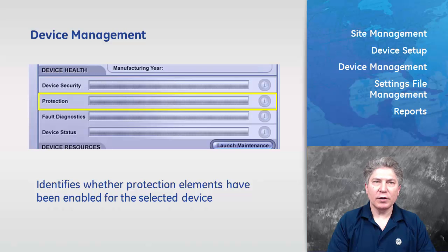If it's yellow, then the CT primary has been configured, but the primary protection is not enabled, the relay is not ready, and contact outputs are not configured. If it's green, primary protection elements have been configured and linked to a contact output. If it's gray, then protection is not applicable for the connected device.